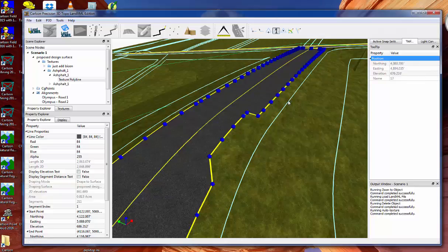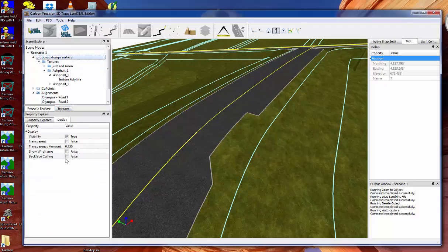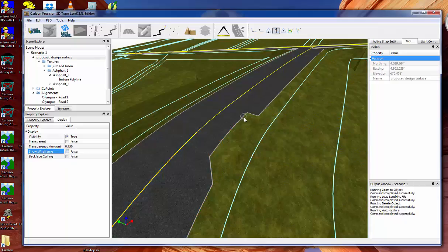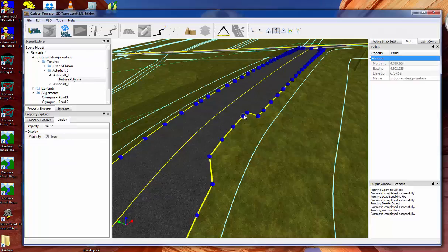What I am going to do is turn on the triangular face snap, and just to highlight what I'm doing, I'm going to show this wireframe, because essentially we know that the edge of this road is going to follow known vertex points. But you don't actually have to look at the vertex points, since we have these nifty little snaps available. So I'm going to highlight this polyline by simply gripping it.